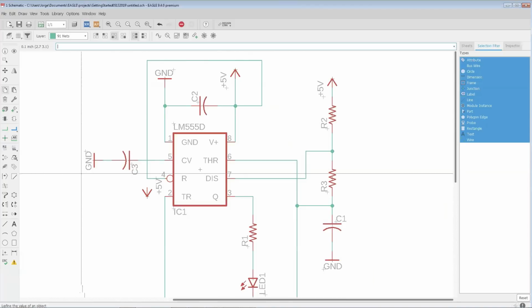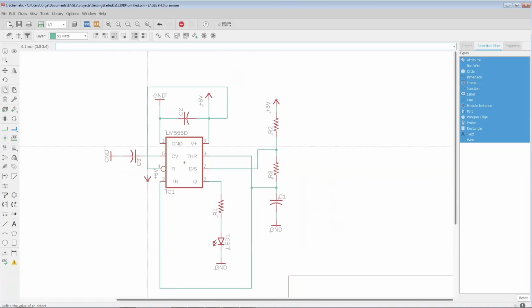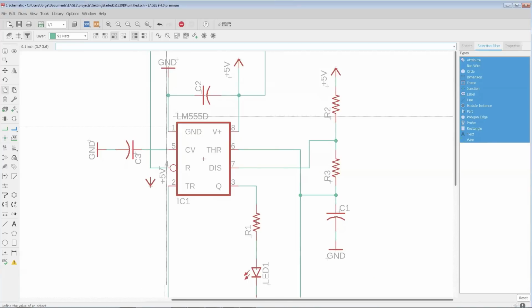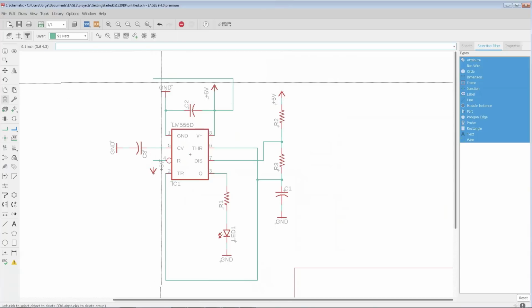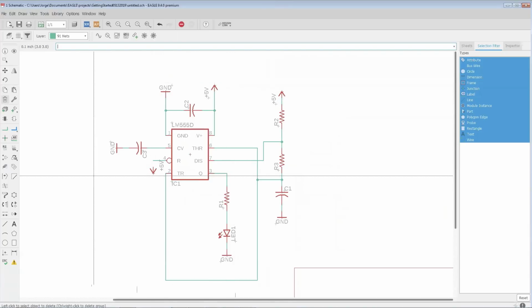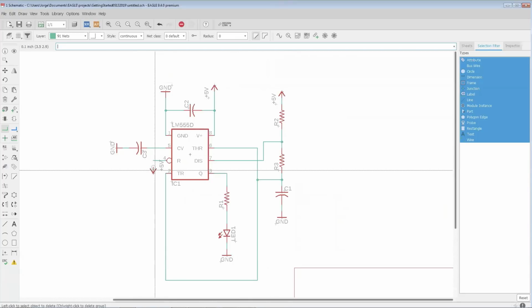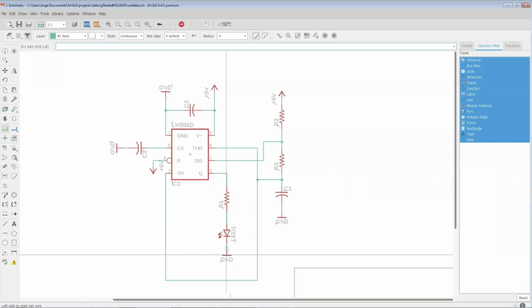And this shows the value of supply symbols. If you notice, we have this unsightly net going all over the place. What I can do is remove that and then just connect right here to there, and that's it. All supply symbols are automatically connected, so you don't have to draw lines between them. They're automatically connected by virtue of the fact that they're supply symbols. So by doing this, I don't have to draw that unsightly net going all the way around here.